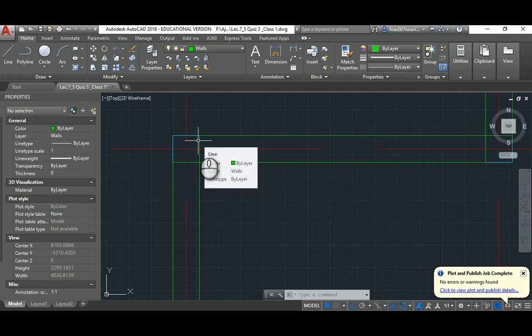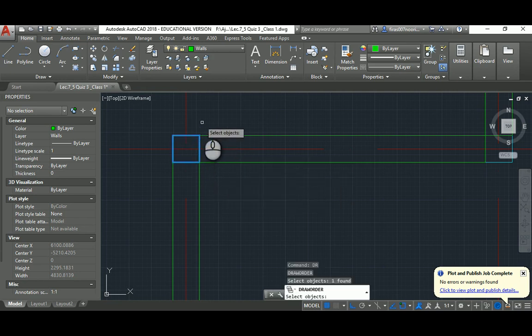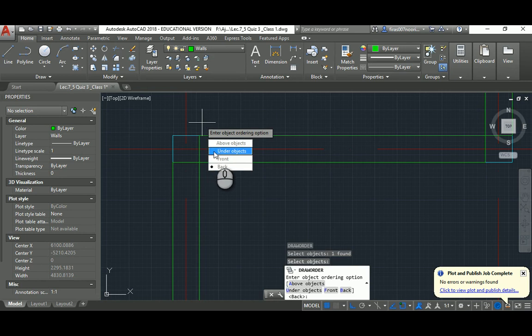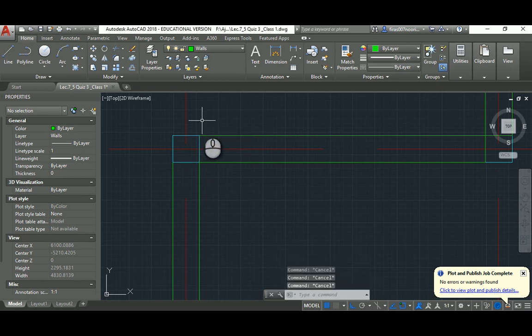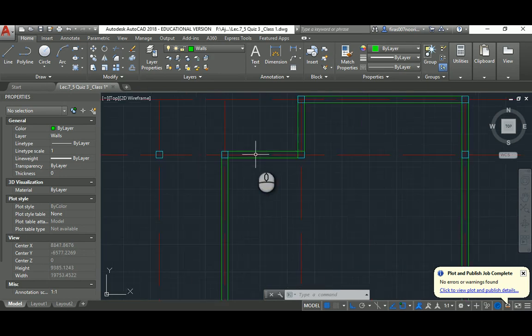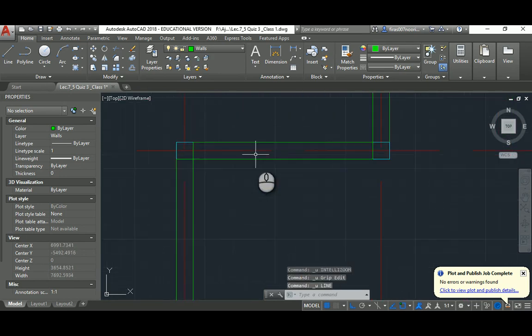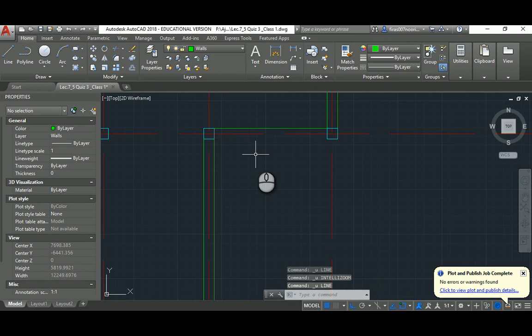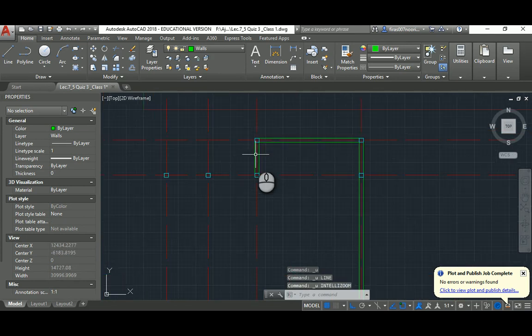So I have to tell AutoCAD which is which, which one you want on top. So DR, draw order, select this column and hit space, and then choose front, which forces AutoCAD to show that guy above the green line, which is probably better than having this one. Anyway, I'm going to do a couple of undos. I don't want that for now. I already did. So there are two ways here to solve this issue, as long as we are working with the column thing.